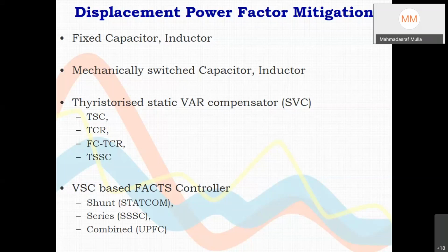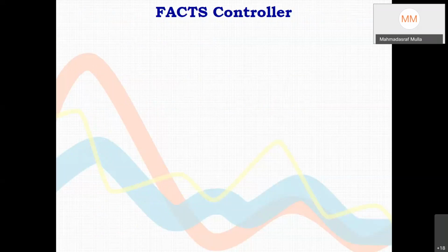So in a smaller volume, you will be able to process a higher reactive power working with this IGBT based arrangement, and that is mainly because of the passive component requirement. So you require less energy storage, inductor and capacitor. So these are the different technologies which we can utilize to mitigate these problems.